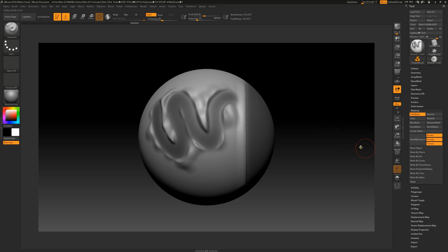To sharpen the mask, use the sharpening tool. Additionally, we can control it via a keyboard shortcut. We hold down the Control and Alt keys, and then click with the left mouse button on the mask. To clear the mask selection, click on Clear, or hold down the Control key and drag a small rectangle in an empty area with the left mouse button.